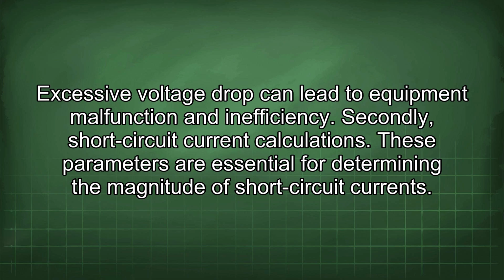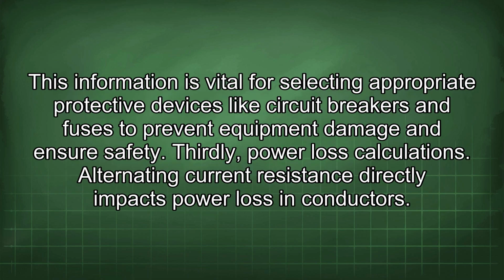Secondly, short circuit current calculations. These parameters are essential for determining the magnitude of short circuit currents. This information is vital for selecting appropriate protective devices like circuit breakers and fuses to prevent equipment damage and ensure safety. Thirdly, power loss calculations.